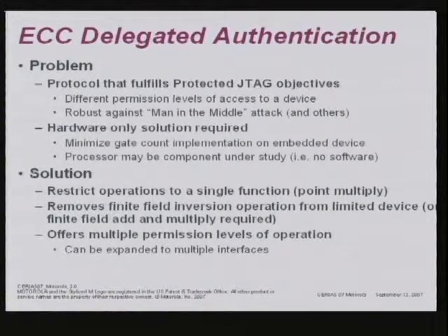So this really can only work if you have a piece of hardware that's on the system before your processor ever starts. And therefore, from a standpoint of dealing with real products, that means I have to minimize the gate count, the square area of the silicon, and I have to reduce the cost to make it a specific function. So in order to meet those requirements of trying to minimize the gate count and cost, I had to look at a protocol that was going to be very effective in hardware. It had to be small.